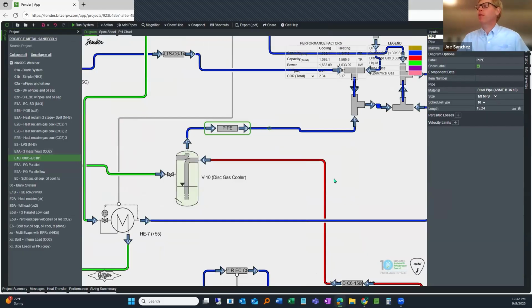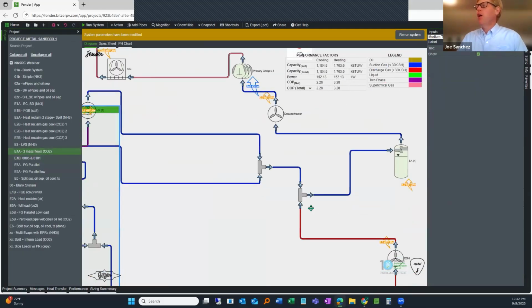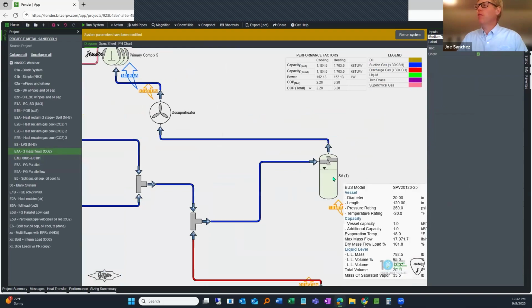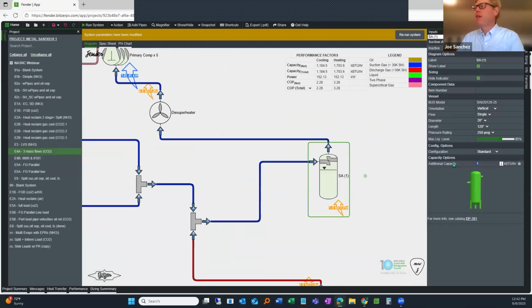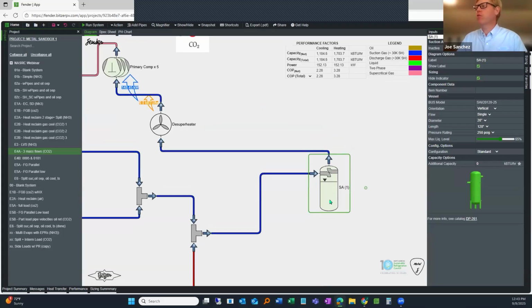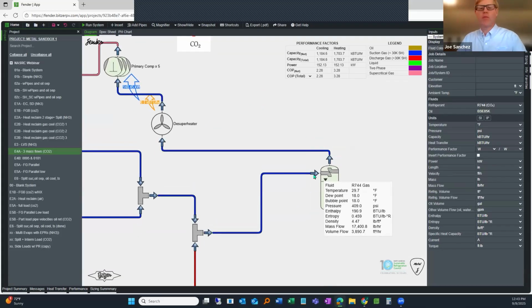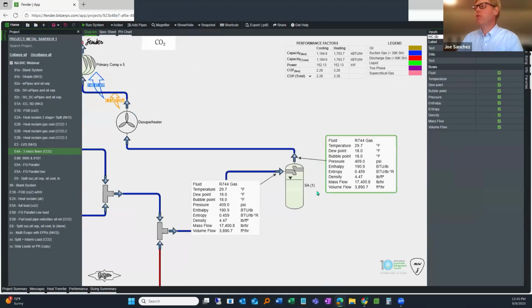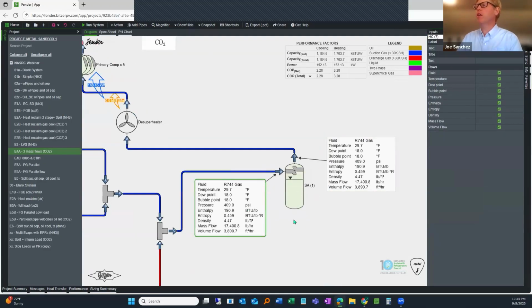By the way, just going back to this example, I don't know if you ever met someone who wants to talk about adding superheat or adding heaters to a suction accumulator in case you're having wet gas back to a compressor. Sometimes you'll meet someone who's like, hey, let's just put a heater around it, or a belly band heater around it.